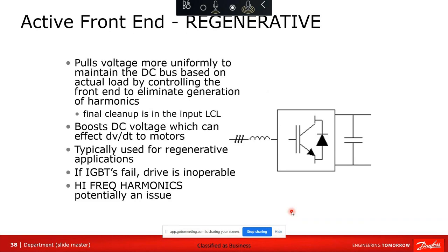Remember, I'm a water wastewater guy. And I tell people, if my raw sewage pump just started spinning faster than the motor wants it to go, I've probably got bigger problems in the plant somewhere. So from a water standpoint, I don't recommend a regenerative drive. There are some issues, not necessarily issues, but there are some things to consider with it.